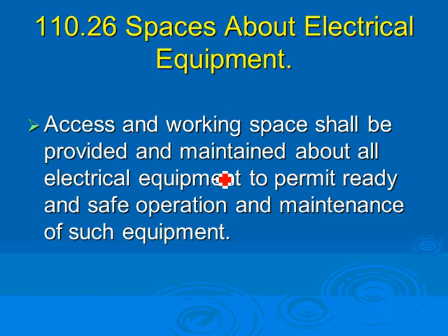So if you look at all the scenarios that we have, typically the largest space needed in front of the electrical equipment is 4 feet deep. The width of the equipment, to the height of 6 feet or the height of the equipment, 6.5 feet. That's your working space. So when you go to the architects, we tell them we need 8. Then we compromise to 6. So now we have 2 feet extra more than what we need. That's for your safety.